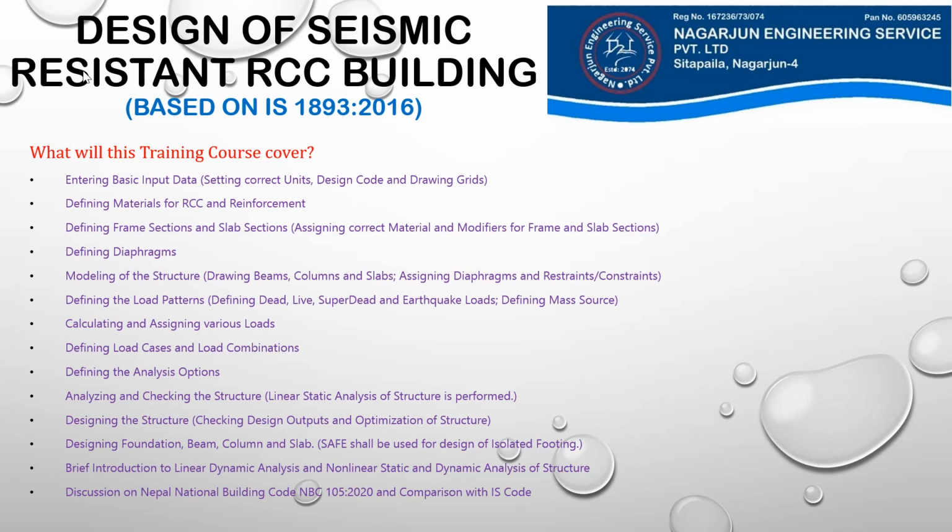This includes defining the beam, column, and slab, and in those frame and slab sections we will assign the material properties that we have defined in the second step, because now the frame and slab sections will be made of certain materials. We have to assign the properties of those materials to those sections. We will learn about stiffness modifiers for frame and slab sections. What does our code say about those modifiers? What happens if we use those modifiers? What happens if we don't use those modifiers?